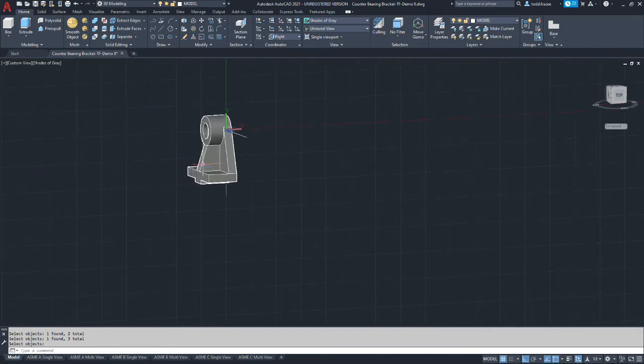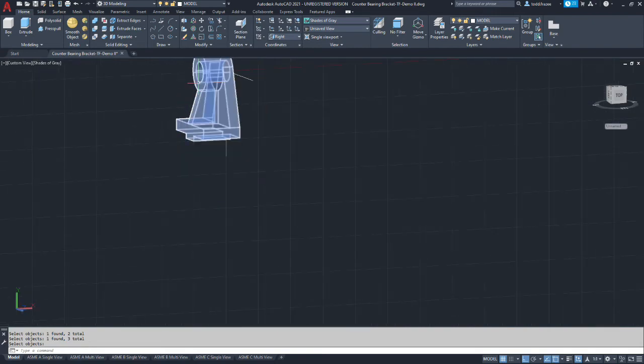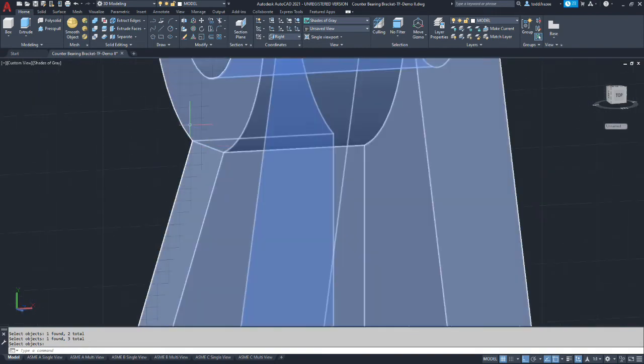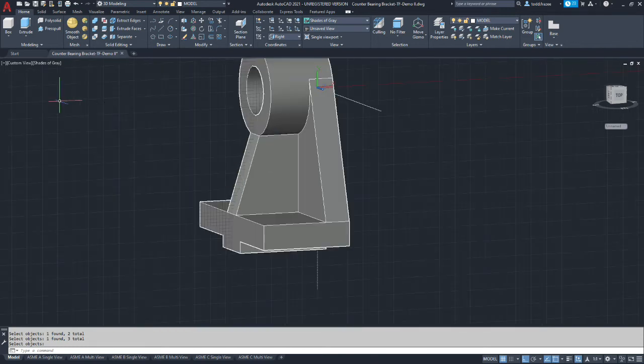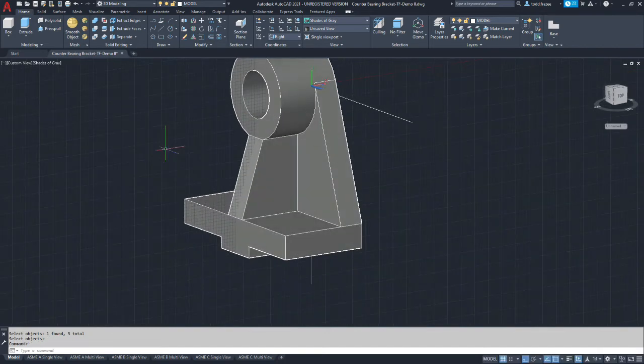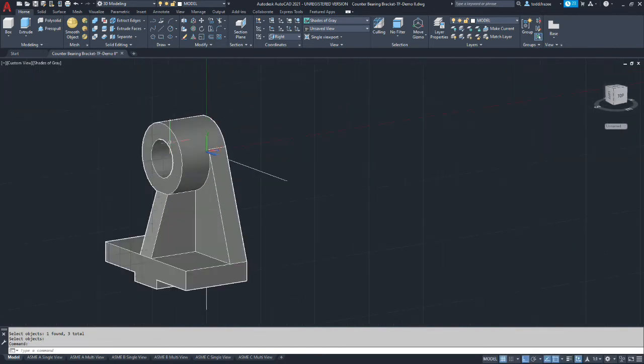Now to take care of this little issue we created for ourselves here. So this would have been an oversized casting. This face was machined down. So there should be a square edge here where the end mill cut the face of the bearing surface. There are several ways to approach this. The way I'm going to approach it is to create a cutting body to cut this.